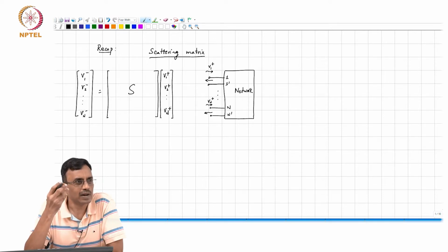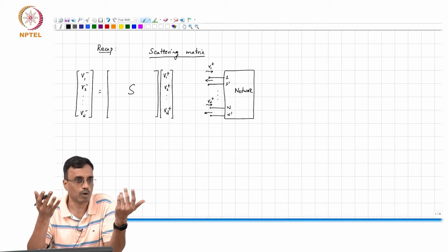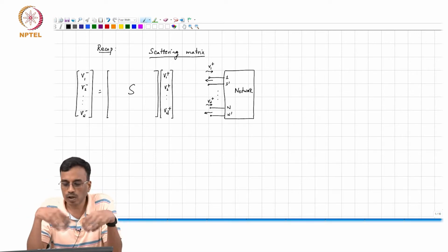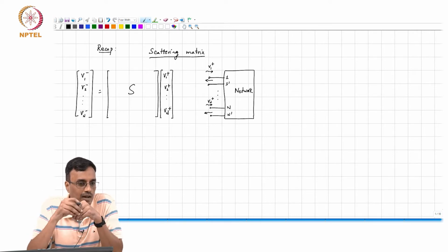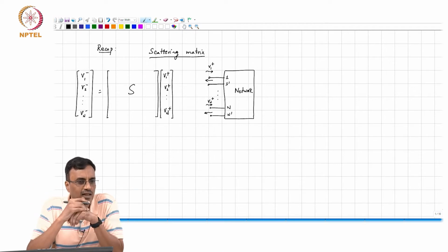And why? Because remember, a transistor is a nonlinear device, and whenever we talk about impedance or admittance parameters, what exactly do we mean? You linearize that transistor about the operating point and get a 2 port which is linear, and then we assume that the signals that we impress on this 2 port are sufficiently small to satisfy the small signal approximation, and then all the other theory makes sense. But if the whole setup is oscillating, and once something starts to oscillate, it only limits when something somewhere in the setup saturates, then it is no longer small signal, and this notion of small signal parameters does not make any sense, right. That is the best case.